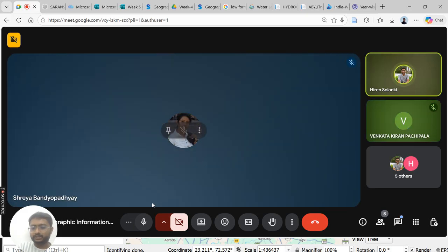So that was for today's class. We have discussed a lot of interpolation applications, not just in MCQs, but in actual data with the groundwater level. Now, if you are interested, you can do the same thing with temperature data, rainfall data, elevation data sets, and try to interpolate various things. Apart from that, you can extract the data from your DEM first of all, and you can try to reinterpolate the same DEM, whether you are able to regenerate the same or not. You can try with that as well. Those things you can do by yourself.